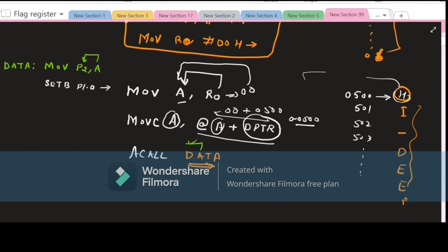This we have to set. As soon as you set it, RS is equal to 1, which means the data register has been selected. Then we need to clear P1.1, which is the read/write bar, so we are doing write. So this is cleared. Then again, we set the bit P1.2 and clear P1.2 again. This is your enable. The enable pin is 1 and then it becomes 0.